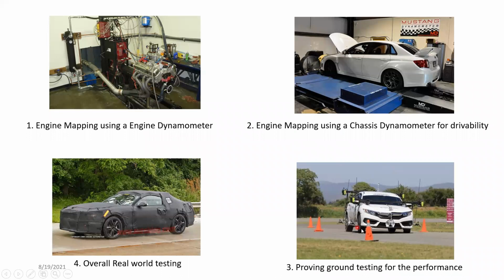Once they do all of these things, the vehicle goes to real world testing. Number 3 is done on a proving ground, where vehicle testing tracks and race tracks have different testing areas, vehicle proving places. Once this is finished, the whole vehicle goes on a road trip sort of arrangement to check the vehicle's overall performance and how it behaves in traffic conditions, temperatures, various driving conditions, highways and everything.